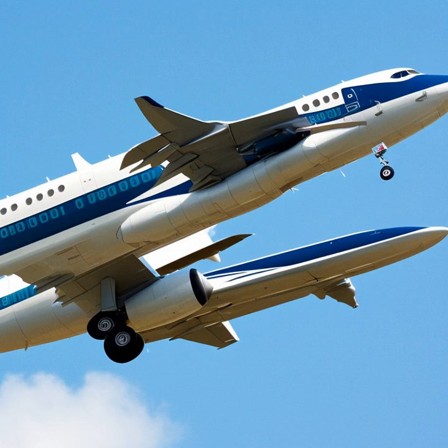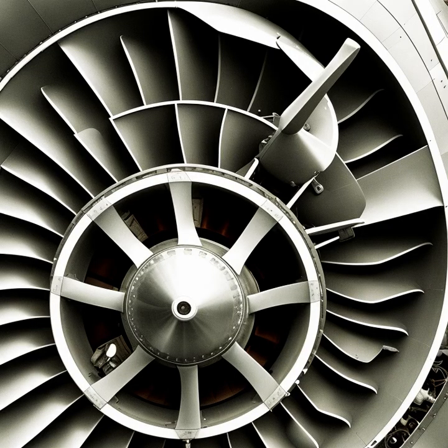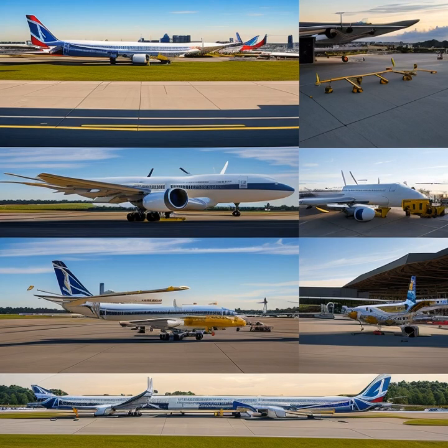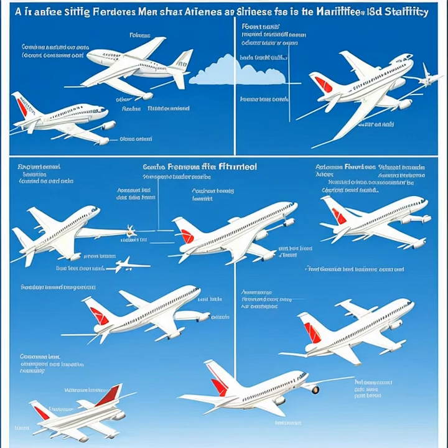Airplanes also rely on the natural stability provided by their tail section, which includes the vertical and horizontal stabilizers. These surfaces help to stabilize the airplane in the yaw and pitch axis, ensuring that it maintains a steady heading and altitude. In summary, the principles of stability are vital for maintaining controlled flight and ensuring a smooth and safe flying experience. Airplane designs incorporate features like dihedral wings and the careful placement of the center of gravity to achieve the desired level of stability.